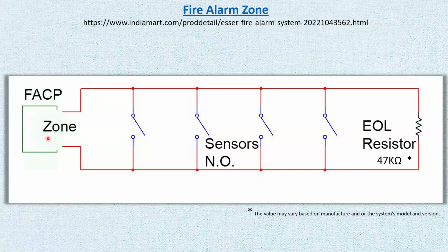Just like that. So of course, whoever is there is going to say, okay, where are the beeps coming from? Oh, it's from the fire alarm. Okay, it says trouble. Call so and so. That could be on the display. So of course they're going to call that number right away and say, okay, something's wrong. No, it doesn't mean there's a fire. Doesn't mean there's not a fire. But something is wrong. Let us come over, we'll see what's going on. Usually it's a broken wire or some kind of a ground problem, right?